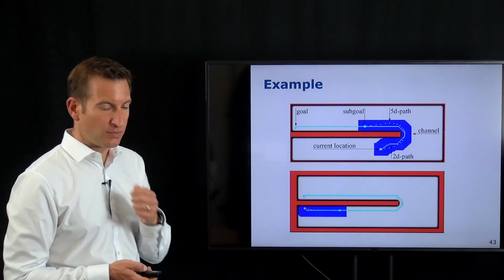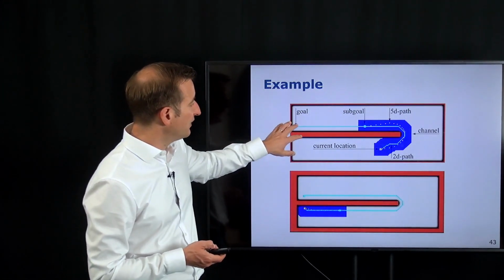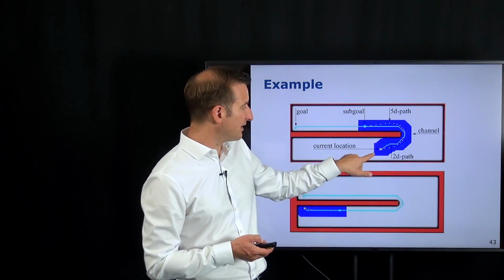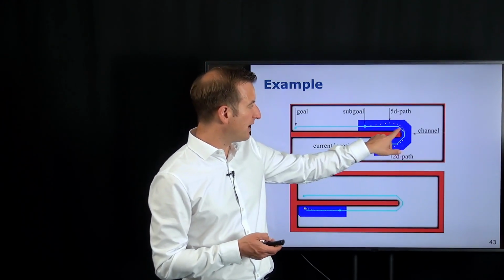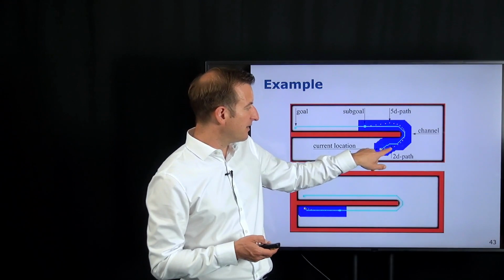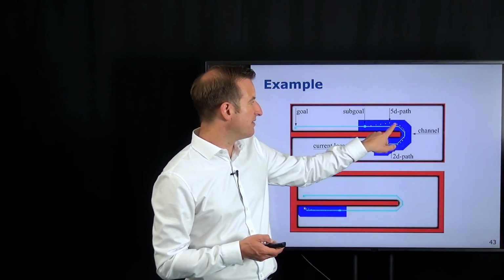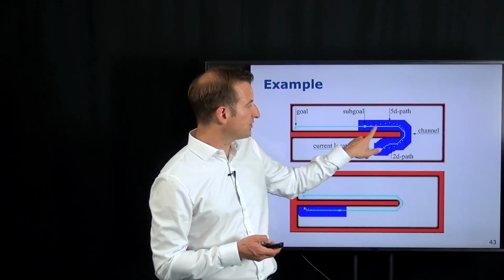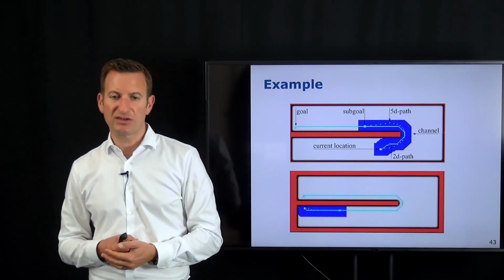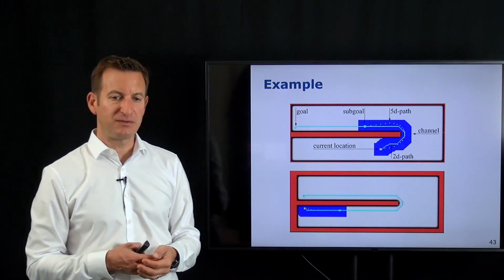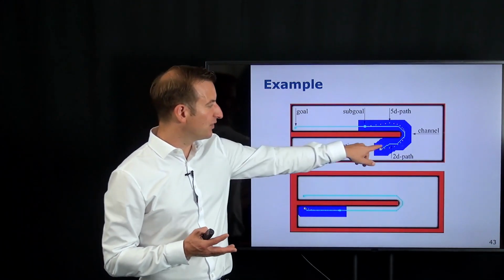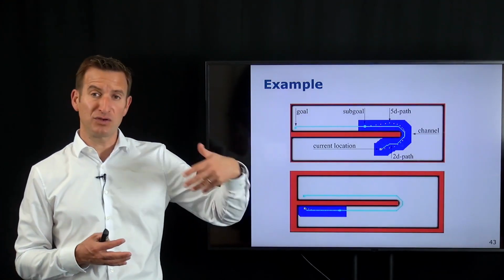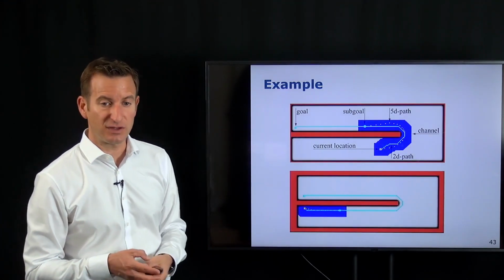So also having a small example over here. Again, what you're seeing is this channel, and then the 2D path, maybe this path over here, and the white path here is the 5-dimensional path, which you can see generates a smoother trajectory because it takes different translation and rotation velocities of the platform into account, and it's not forced to this 8-neighborhood, because the transitions are computed based on translation and rotation velocities.